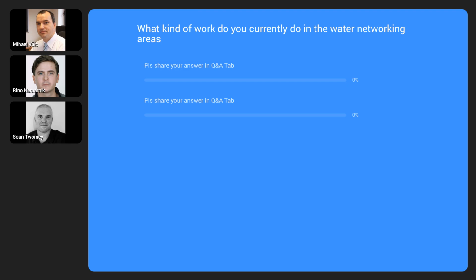It is not meant for different types of infrastructure, but of course you can use it. You create a new system type and you rename it to cooling water or heating water or whatever. But you are limited to the functionality that you have for designing the systems which it is meant for. So you have your pipes, you have your manholes, you have your trenches, you have your functions for detailed design in plan and profile.